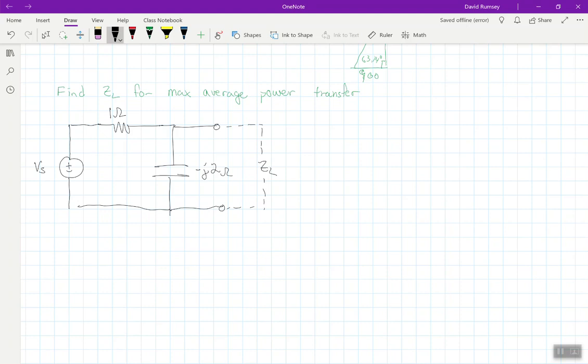So, we're looking at a circuit like this here. And I did this on purpose because it looks very similar to the previous example. And I see a lot of people just combining this in series. That's wrong. Remember, when you're finding equivalent things, you need to turn off your power supply, which a voltage source becomes a short.